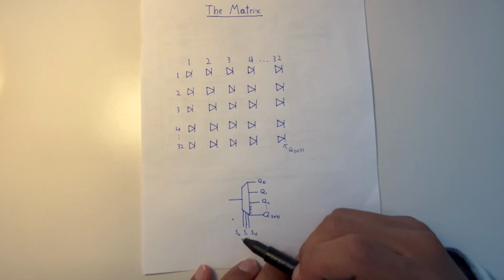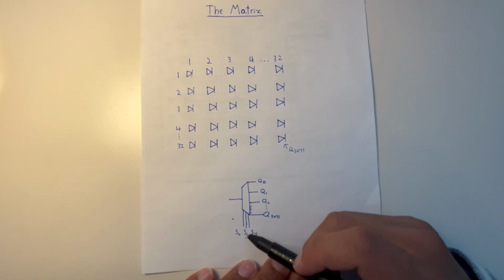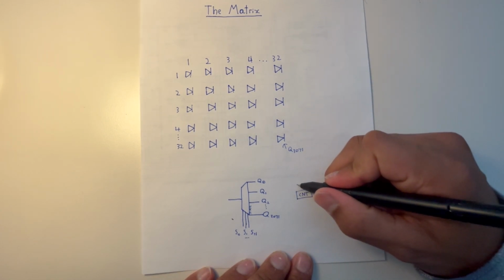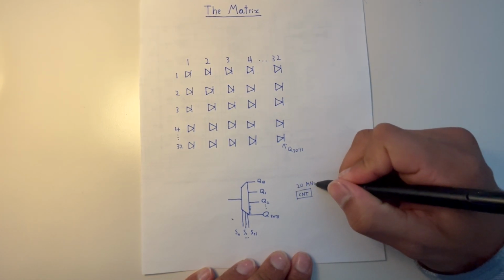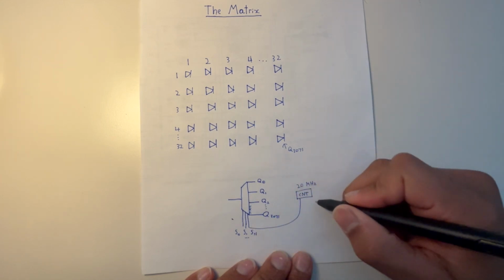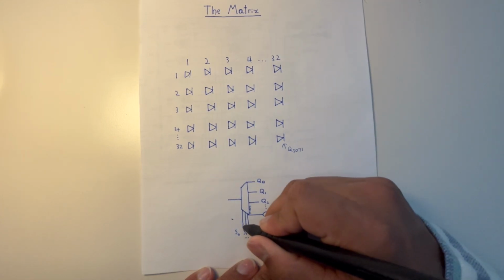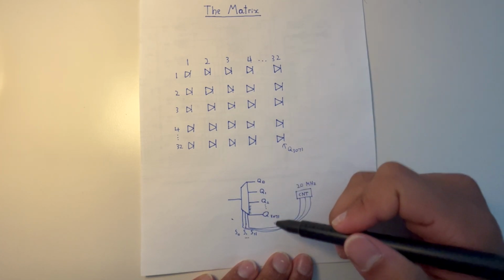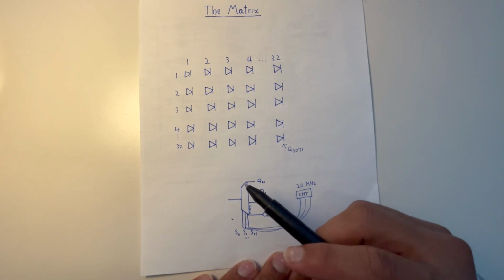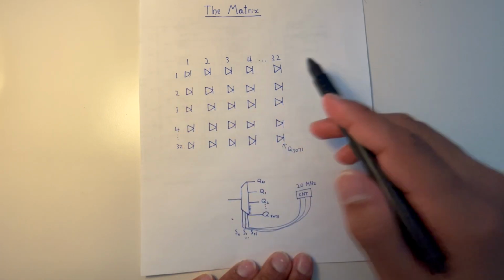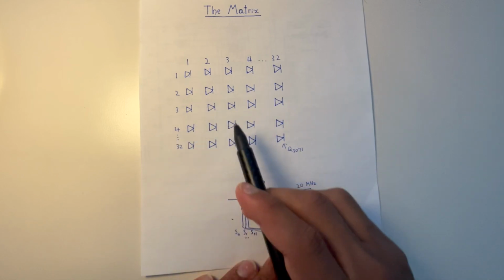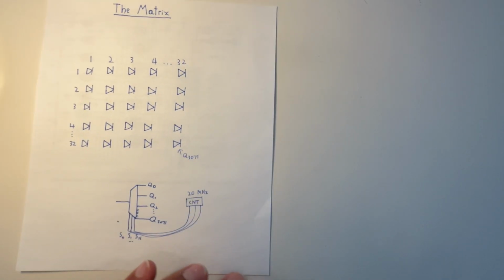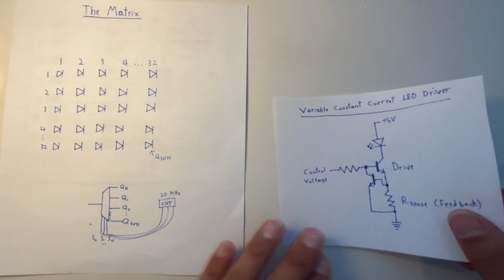Q3071. So the select pins of the demultiplexer are run by a 12-bit counter that's clocked at 20 megahertz, and that's fed directly into the select pins. So what that means is the demultiplexer pins are constantly being changed. It's always going from 0 to 3071 really quickly, which essentially means that the demultiplexer is always scanning across rapidly at around 20 megahertz. So the penultimate consideration to this project, I'll set this aside for now, is what drives the input of the demultiplexer.